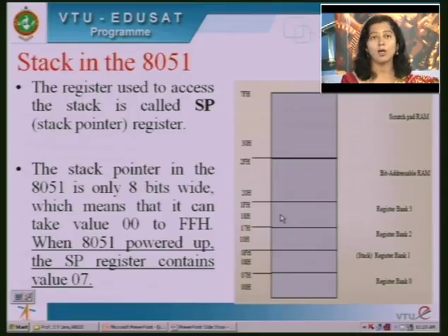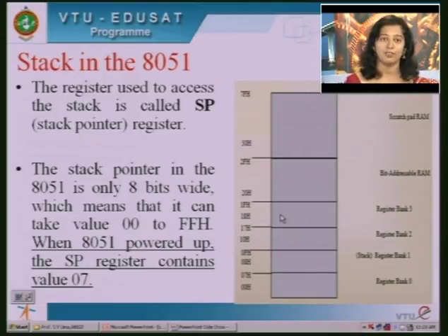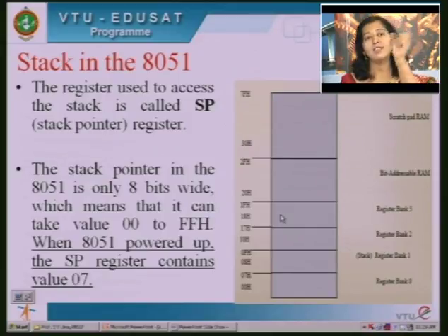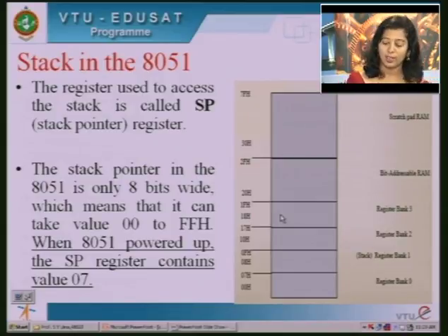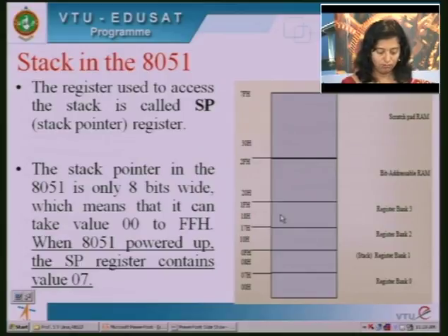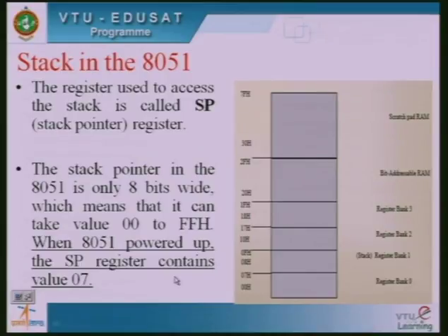All the others on top will fall off. So it's always better to take out first what you put in last. You go on stacking data one on top of the other. Whichever data you put in last, the stack pointer will be pointing to that data and you have to take out that data first. Okay. So that's how you have to take out the data.